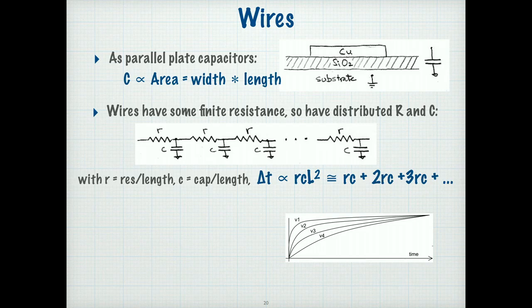Now, if we look at a wire in cross-section across the chip, there's the substrate here, which is typically grounded or connected to VDD, depending on which part of the chip, but it's one of the rails. Then there's silicon dioxide. Remember, we use silicon dioxide as an insulator. And then there's wire. The wire typically these days is copper in most of our ICs. Used to be aluminum, but now we use copper. So it's a good conductor.